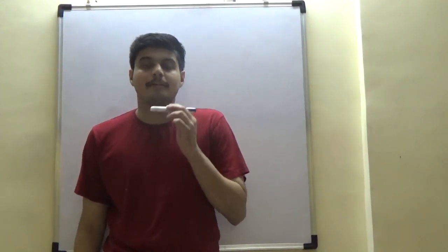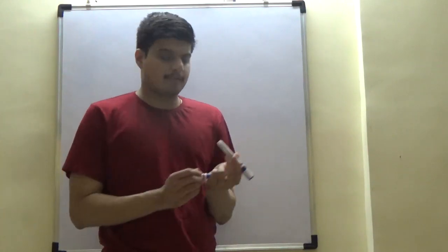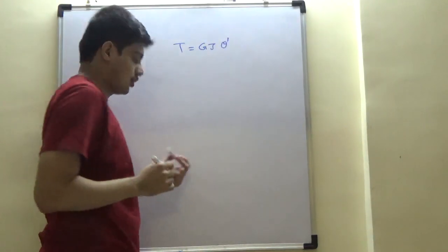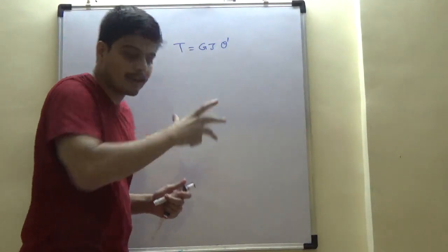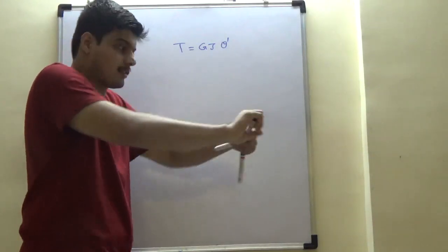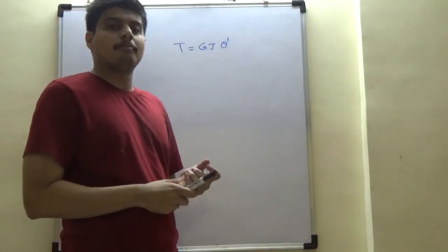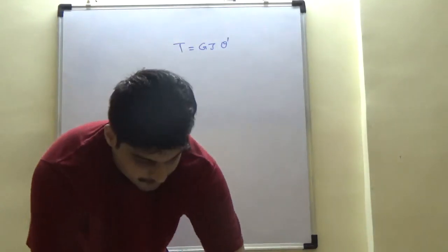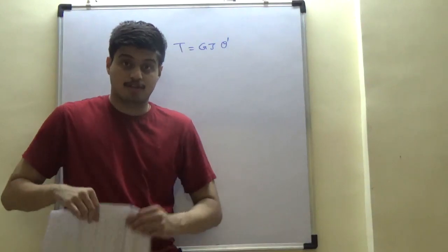as a more important point. Just to summarize one concept, we looked at this concept of torsional rigidity, right? Where we use this equation T is equal to G J theta dash, where J is a constant, G is a material property, and T is the loading condition. What we basically said is that for a given twist, G is of extremely important value because that dictates how much twist is going to happen. And this is extremely important in terms of aircraft structures, by the way.